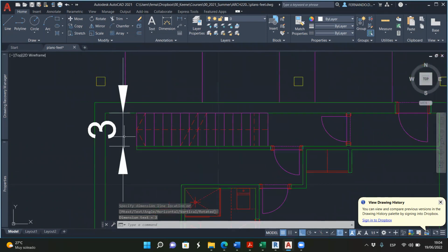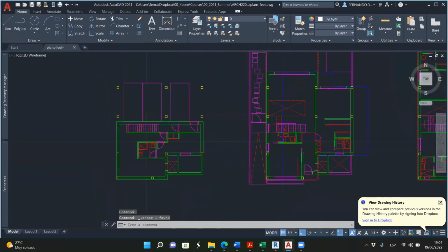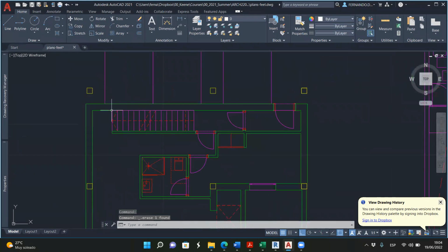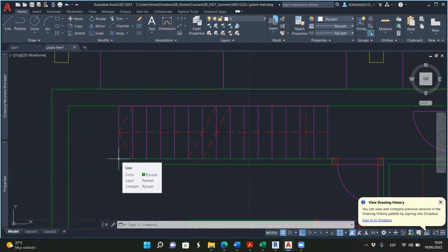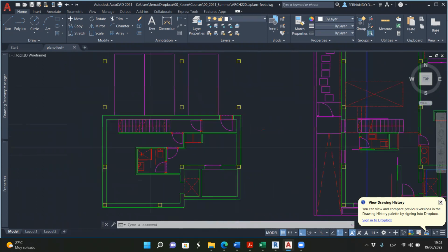Okay, so if this is 3 feet, we're good. When we export this into Revit, probably the scale is not the right one. So we need a fixed dimension we can trust, and then we can scale the AutoCAD file in Revit so that the dimensions are accurate.